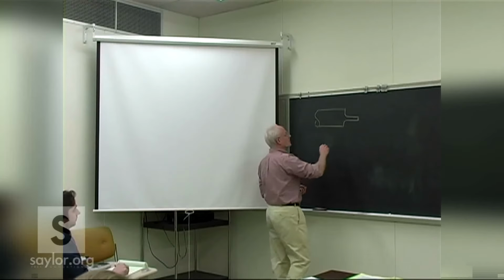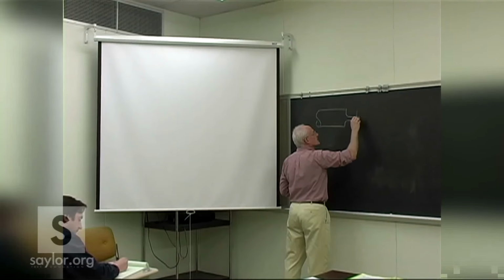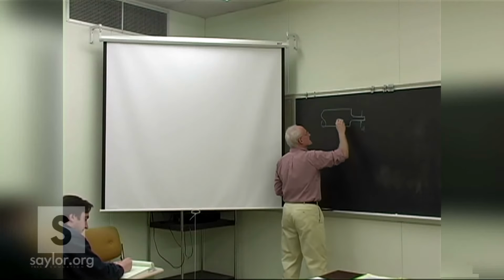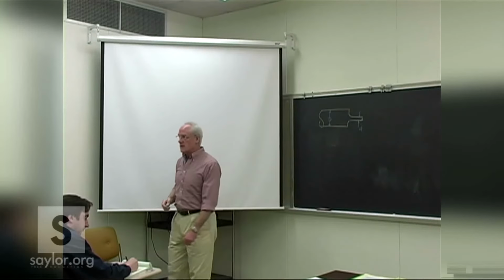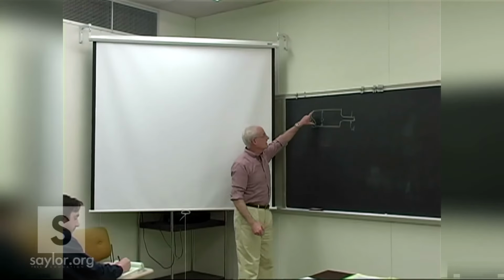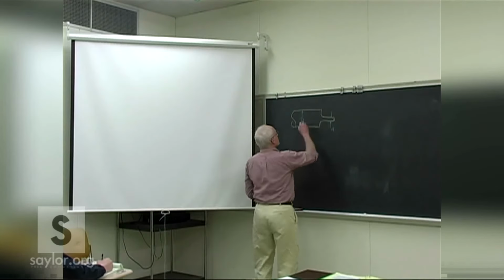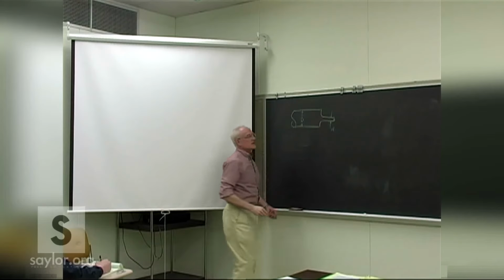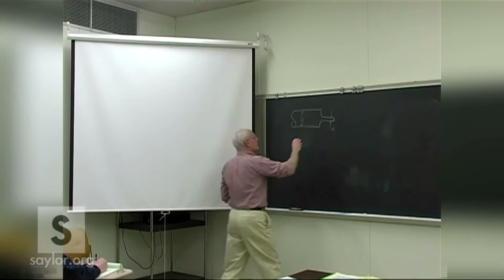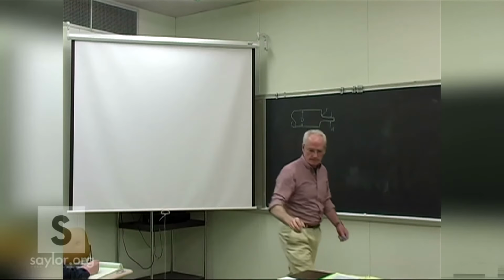So depending upon what the load is and the geometry of each of these, it's no surprise, I don't think, that it depends upon the major and minor diameters of the piece, because whatever stress is felt in the large part, that same amount of stress is going to have to flow into the smaller one, causing stress concentrations. And it also depends upon the radius of the fillet.